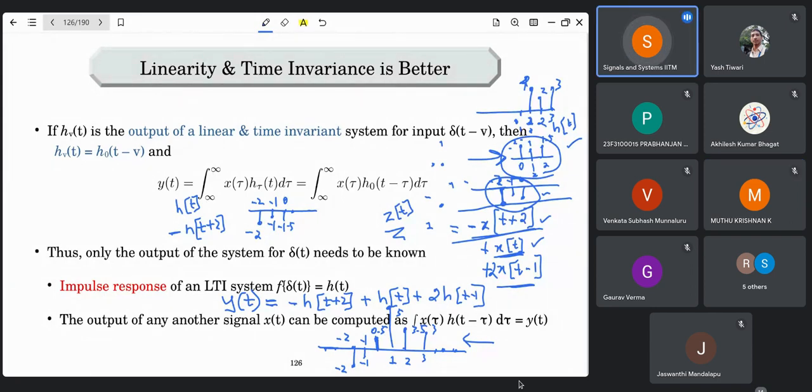It depends upon what test cases you are giving. What we know from the theory of signals and systems is that the best possible test case is the impulse. If you give some other signal, we don't know if that will be sufficient. It may or may not be. Later we will see that you can give a unit step signal, and that will be sufficient for certain cases, not always.